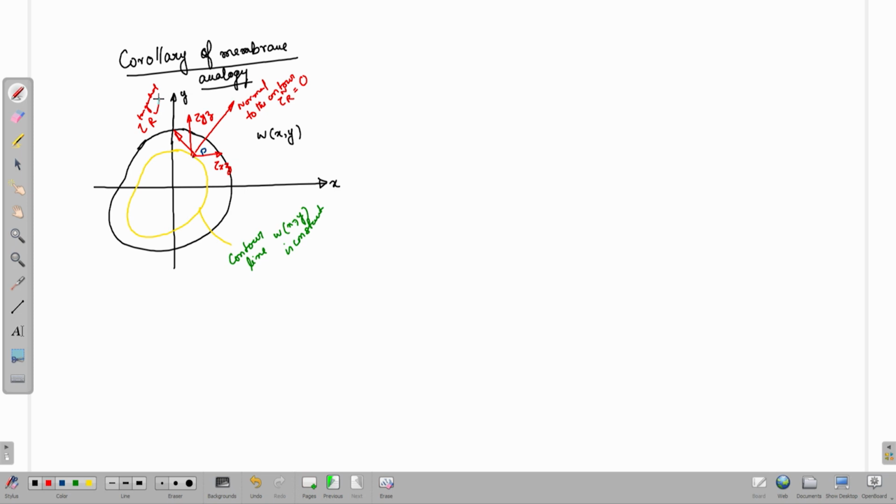Okay. So, suppose I need to find the shear stress at a point on the cross section of the shaft, then I have to imagine a contour line through the point. Then I can say that the total shear stress at the point is only in the direction of the tangent of the contour, and the resultant in the other perpendicular direction is 0. This knowledge is very beneficial, as we will see later when we solve examples.